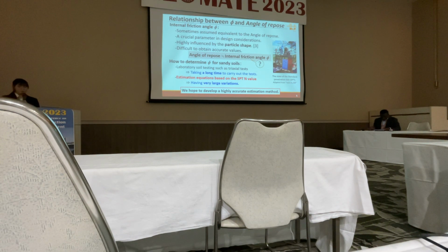There are 2 main methods for determining phi for sandy soils: laboratory soil testing and estimation equations based on N value of the standard penetration test, SPT. However, both methods are disadvantageous when used in practice. We have focused on the estimation equation using N value, so we hope to develop a highly accurate estimation method.